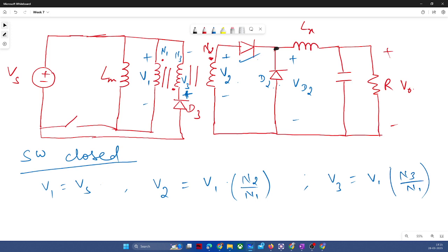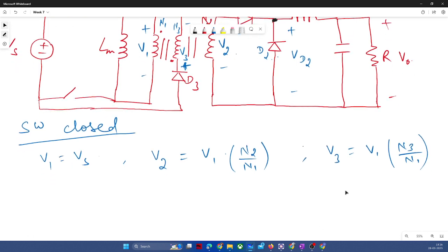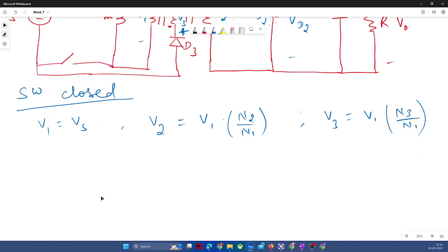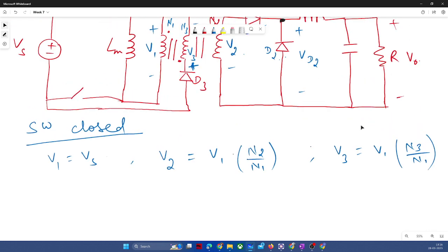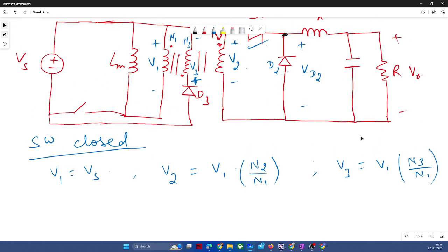I think in this configuration, yeah, you can proceed with that. If you increase the value of N3, you can double the value of N3, so that you can double the value of V3. The stress on the switch will be more, but we can reset it earlier, with a larger voltage across the switch. Definitely, but you have to pay a price in terms of switch rating. So here the advantage will appear if smaller voltage forward converters are there, then we can take that type of risk. Definitely, because current will die down faster with a larger voltage across that winding. So let us see the VD3.